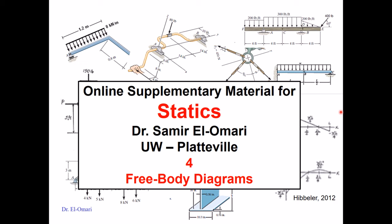In this session, we learn how to draw free body diagrams. Free body diagrams are very important in solving complicated statics problems. It actually makes it simpler once you see the system and you see the reactions, and then you can continue by finding support reactions or drawing shear moment diagrams. But the first step is always drawing a free body diagram.